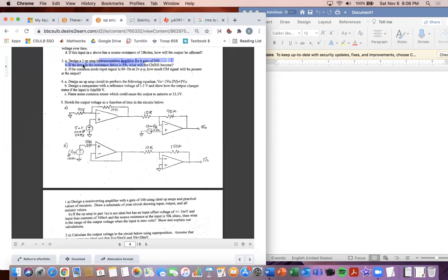Part B is easier. Okay, so part B, you're going to analyze the contribution from this one, and then you're going to analyze the contribution from this one. Here we go, because this one luckily has just one voltage source for this entire circuit. Okay, I remember this. If you guys recall, this is just a voltage follower circuit. And so V in is going to equal V out, and it ignores this resistor right before it.